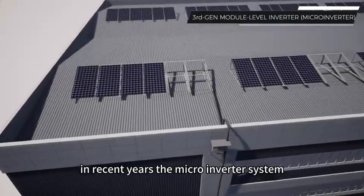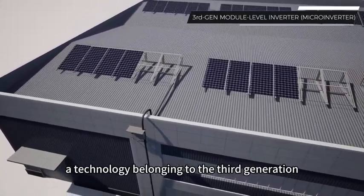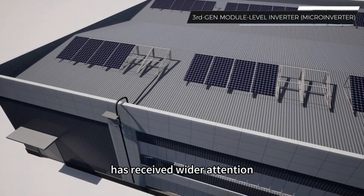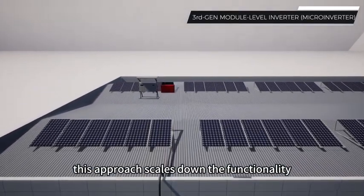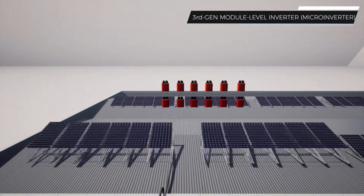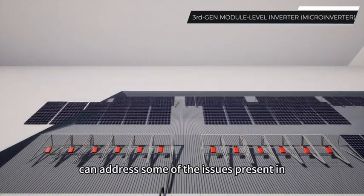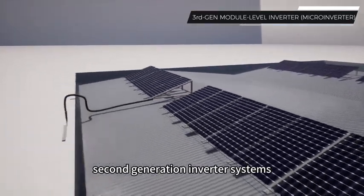In recent years, the microinverter system, a technology belonging to the third-generation module-level inverter technology, has received wider attention. This approach scales down the functionality of traditional string inverters to individual modules. By controlling each module individually, the microinverter can address some of the issues present in second-generation inverter systems.